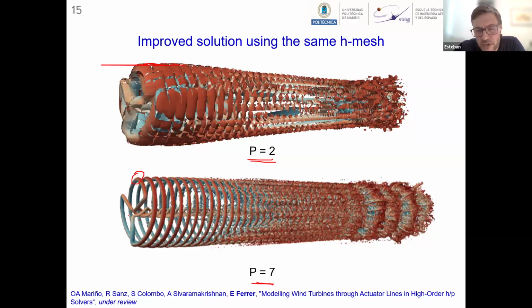This is with no tower or nacelle, just the blades rotating. What's interesting with these cases is that you get a clear tip vortex, which eventually transitions to turbulence, and then you get much more mixing. This is actually a way to check the accuracy of the results. The longer these tip vortices are maintained, the fewer numerical errors are in the simulation. This is something that people typically check.